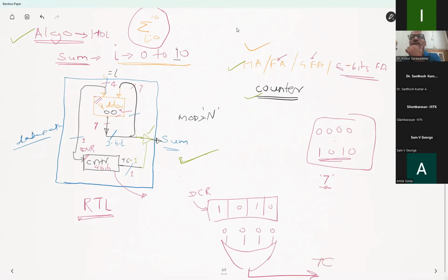And because this is going to produce terminal count equal to 0, we need to immediately change this to an active low tri-state buffer, so that for the rest of the time it will not be sending garbage data at the output. That is a small change which one has to take into consideration as per the design philosophy.